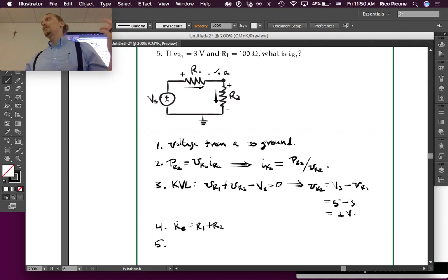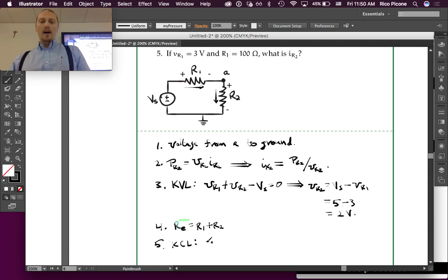Now, you could just sort of try to intuit your way through it, but I would say if you try to think a step or two ahead, it'll help. So I will say KCL. KCL tells us that if we sum up in node A all the currents going in, we have IR1, and then out is IR2, right?